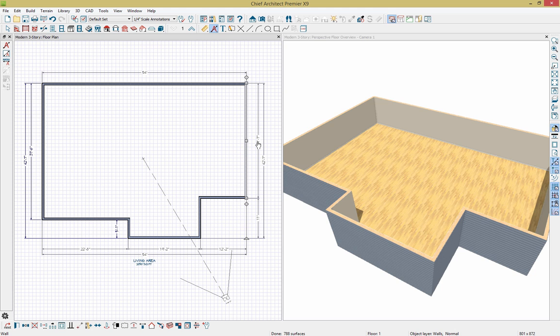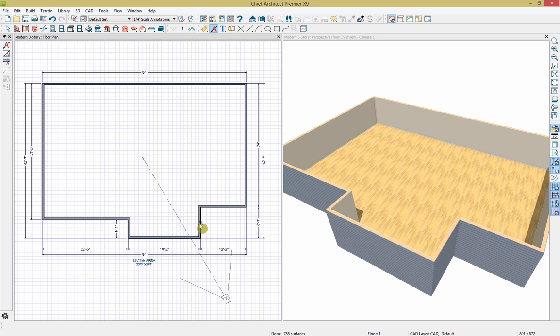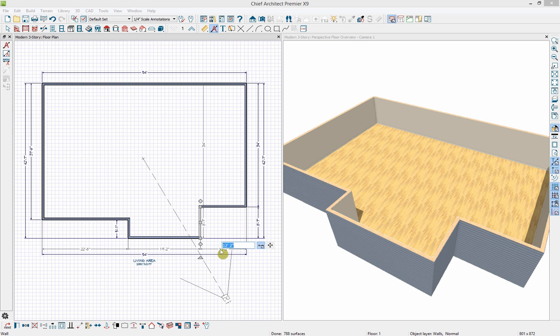So I'll single click on the parallel dimension to that wall, and we're going to tell the wall to lock this end and extend this bottom end, which you can see by the little indicator here. You can modify that to act a little bit differently if you'd like. We're going to change that to 34 feet. So I'll put the foot marker in there. With the program, it will automatically think in inches. So put the foot marker in there or type in inches as well.